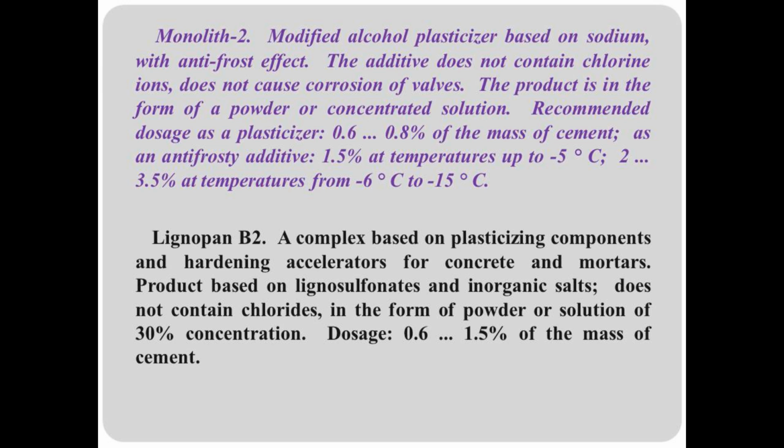The product is in the form of a powder or concentrated solution. Recommended dosage as a plasticizer: 0.6 to 0.8% of the mass of cement, as an anti-frosty additive,